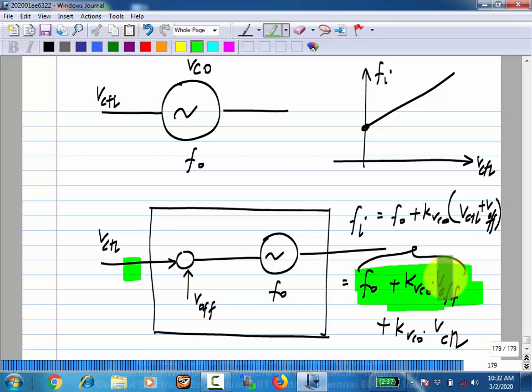If I add a DC offset, it will change. So now somehow the trick is that I have to add a DC offset and keep on varying it until my new free running frequency becomes exactly equal to the frequency of the transmit data. Is this okay?